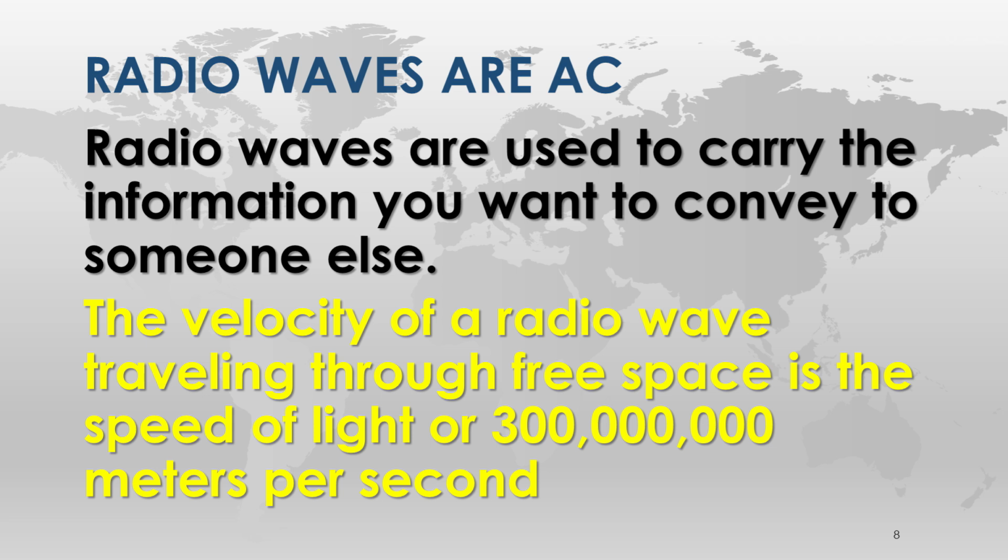I wonder if elevation affects that. I'm sure it does, because the density of the atmosphere is less. Okay, that's right. So when I get up to 12,500 feet in my Cessna, with the throttle at the firewall, I get 45 to 50% of my power available because there's just not enough air.